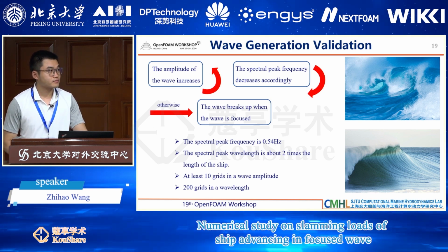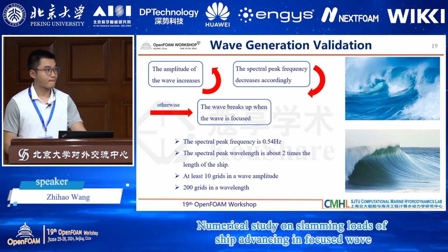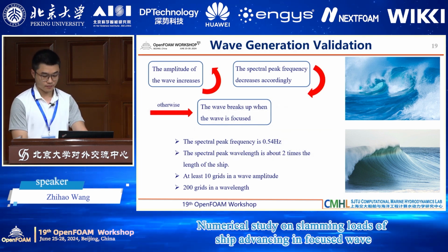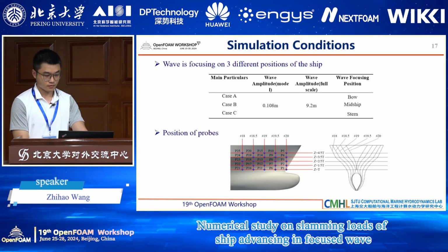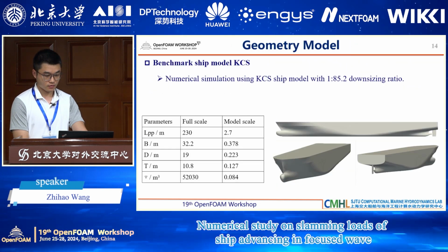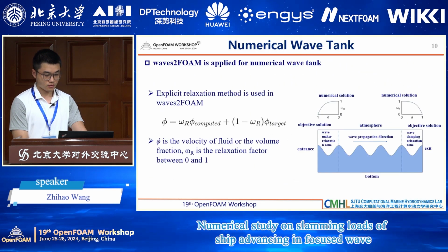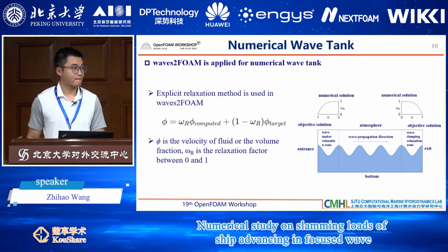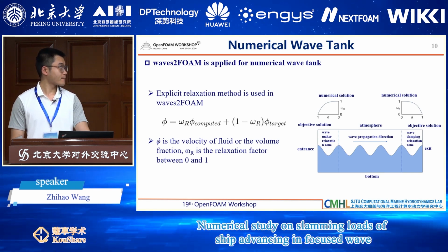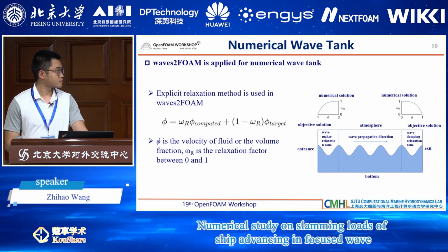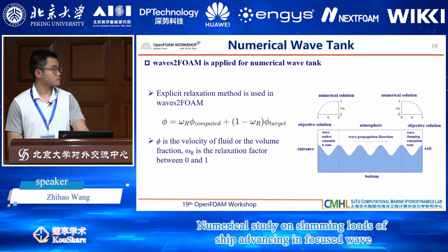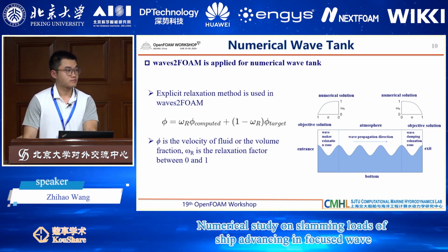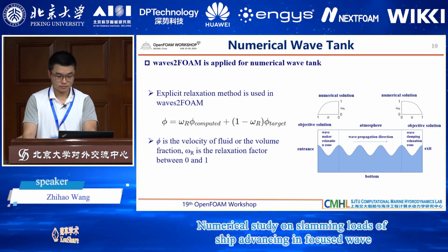Okay. So there are codes like, for example, Fine Marine, which will use a wave generator to create the wave. The problem with that is that you have to have quite a long period for the wave generator to create the focused wave through motion. And then we have to follow that wave until it comes to the ship. What the relaxation zones do is they will calculate the analytical shape of a focused wave at a point in time, and that will be imposed onto the solution.